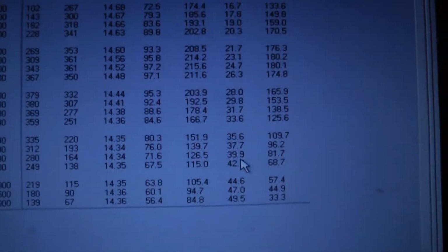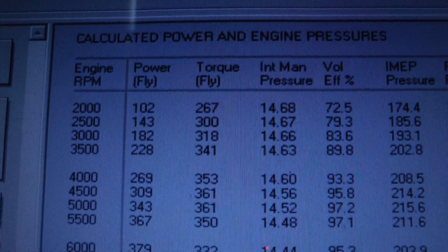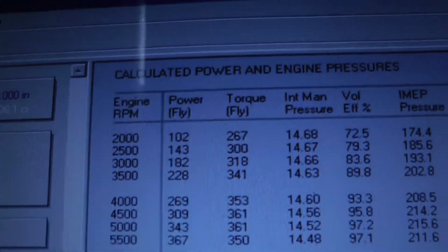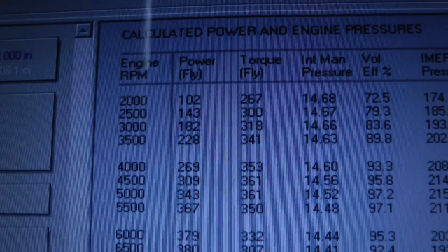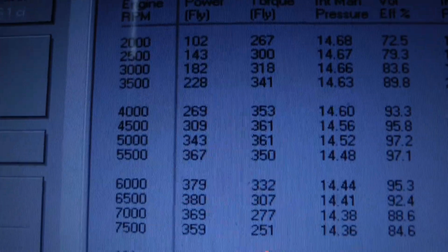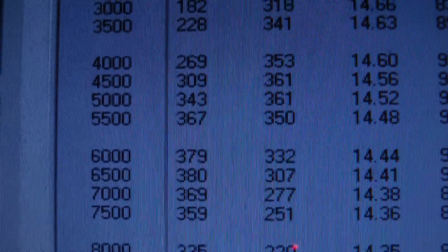So let's look at the numbers. Coming down right at our converter, which will probably be more because of the plenum, you're almost at 300 foot-pounds with the lockup converter all the way up. So we're hitting about 380 at 65.